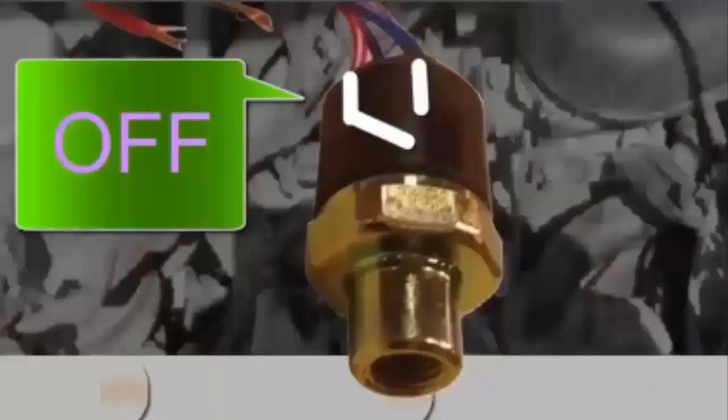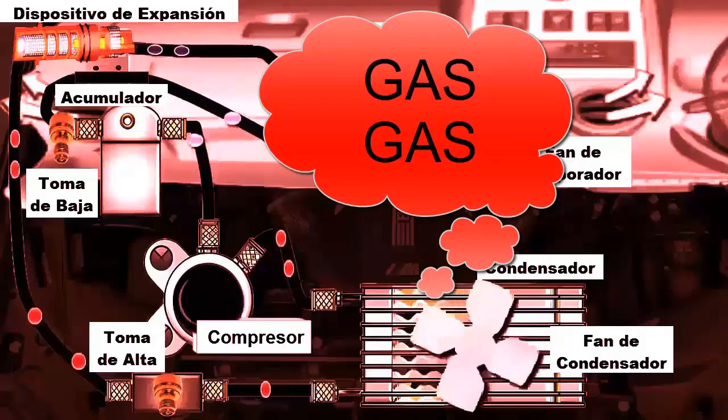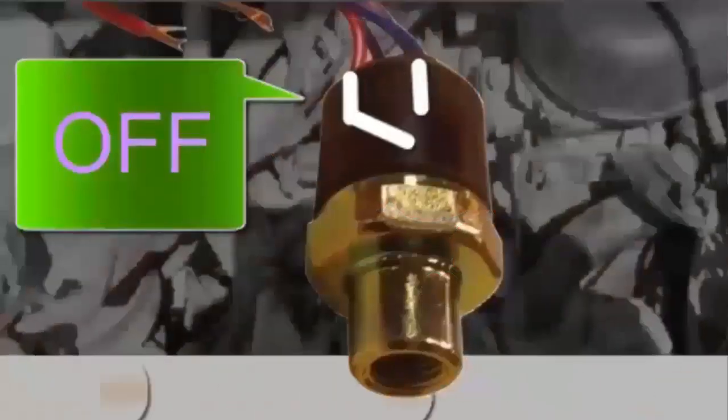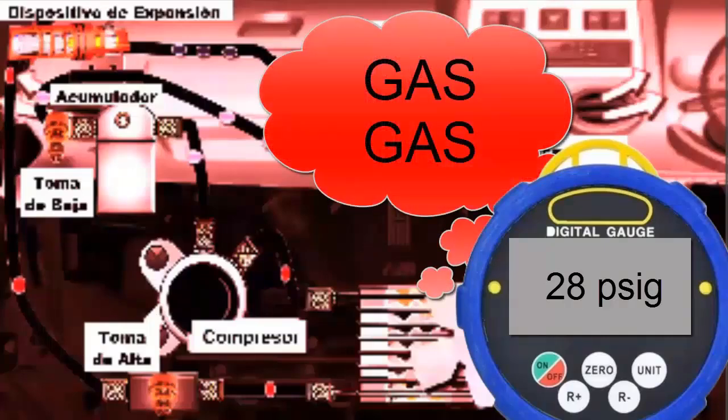Additionally, in cases of significant refrigerant leakage, if the system's pressure falls to dangerously low levels, the compressor will deactivate if it is already running. If the leak is severe enough, there will come a point where the compressor will never activate, as the low-pressure switch will prevent it.